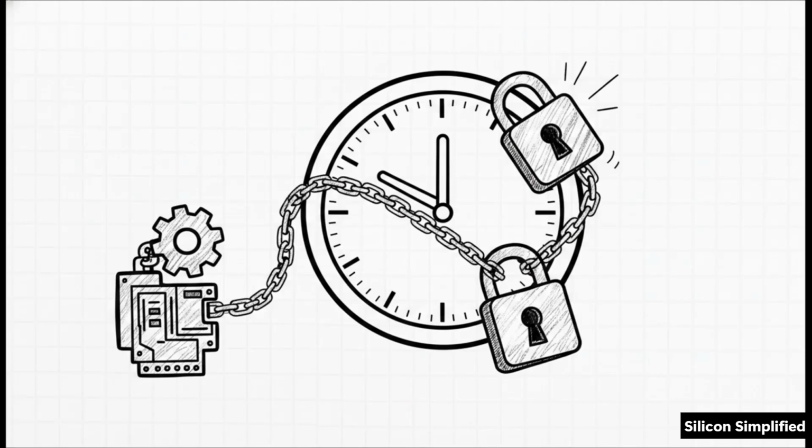If a component knows it needs time to complete a task, it raises an objection right at the start, at 0 nanoseconds. This objection literally prevents the simulation from abruptly moving to the next phase. So, for example, if component A takes 40 nanoseconds to run its test, and component B needs 100 nanoseconds, they both raise an objection. Component A drops its objection at 40 nanoseconds, but the simulation stays in the run phase because component B is still holding its lock. It's only when the very last objection is dropped at 100 nanoseconds that the simulation safely moves on.